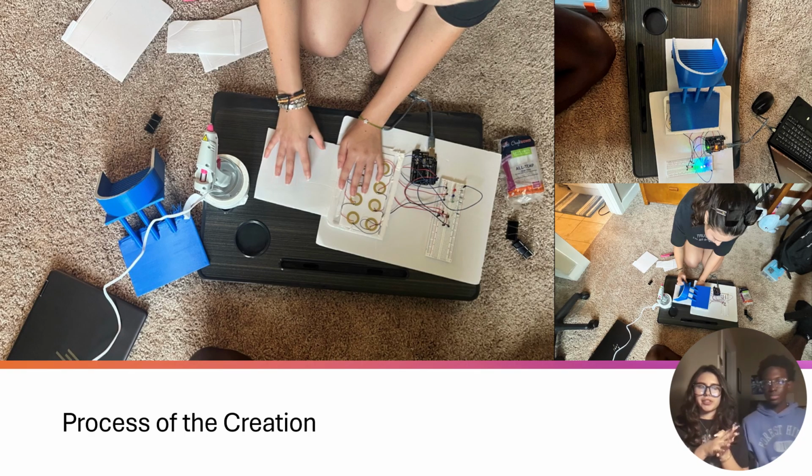In the process of our creation, we wired those piezoelectric pads into our circuit and connected them to an Arduino just to help regulate and display the output. When the Arduino senses the voltage produced from just stepping onto the pads, it activates small LEDs. These LEDs lighting up, showing that we're successfully converting the user's or customer's wasted leg bouncing energy into useful electrical energy.